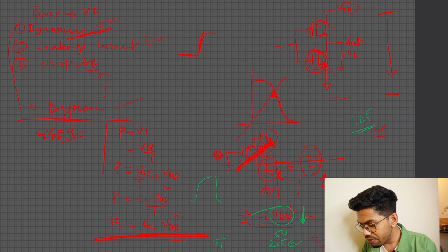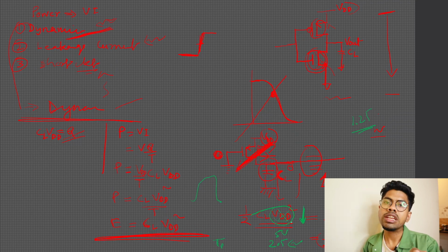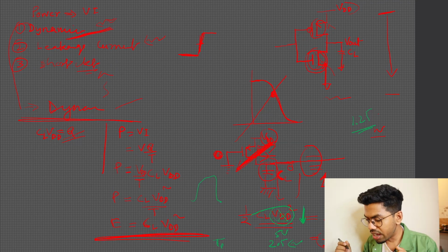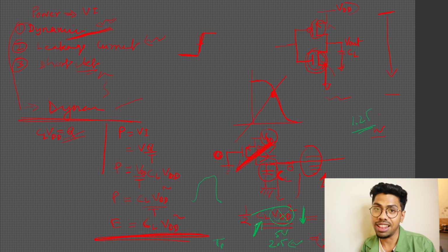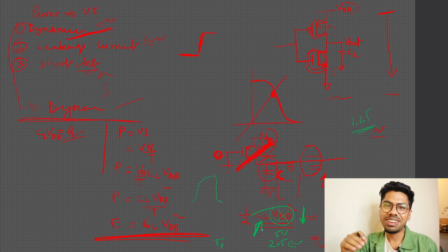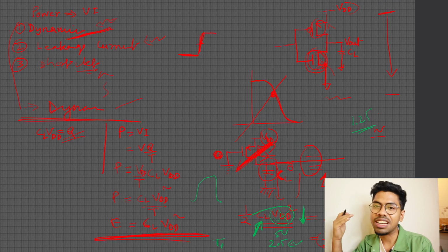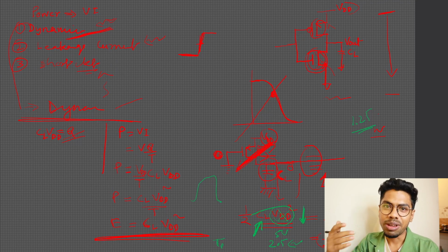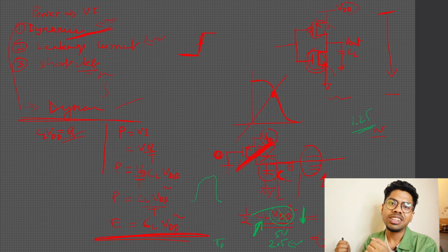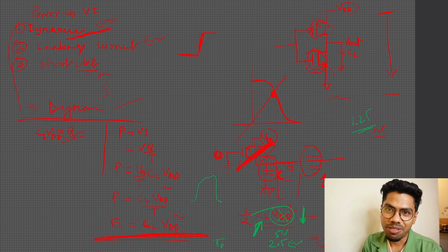So that means VDD is probably not in the designer's hand, most probably, right? So then what is the extra thing we have? That is, you can reduce your CL. That is the most important thing, and there the PD engineer, the physical design engineer, comes into play, because their layout will decide how much capacitance you have, right?